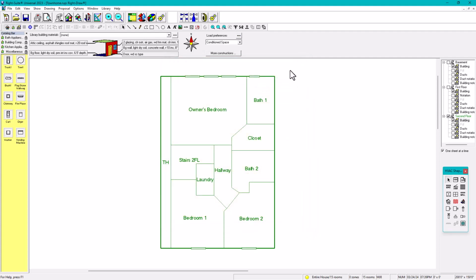We go to the floor plan, right? We have the second floor, the first floor, and the basement. Where is my equipment located? Okay, so what we're going to do is the second floor. In the second floor, we're going to enable the ducts, right? On the tray, we need to enable or check the ducts. In here, we check that, and we're going to be able to see that this only shows diffusers. See the diffusers right here? I mean registers. Only registers there. I don't see the system here.